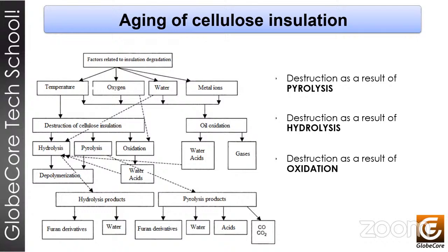With a moisture content of solid insulation of 0.3%, paper insulation is considered well dehydrated and having a full service life. Then, with a moisture content of solid insulation equal to 1%, the aging rate increases 6 times. A standard allows paper insulation to be moisturized to 4%. If all other effects on the insulation and other operation factors are equal, we find that with such moisturizing of the paper, compared with the basic value of the moisture content, the aging rate increases by 48 times.